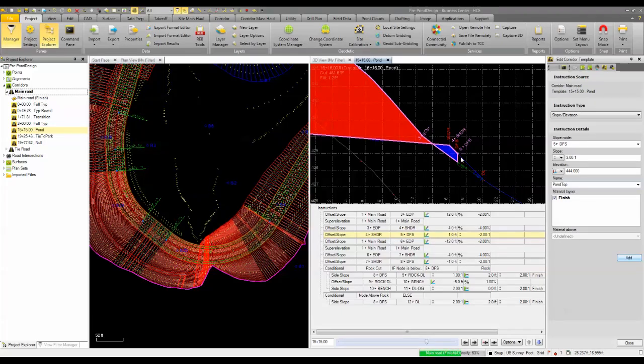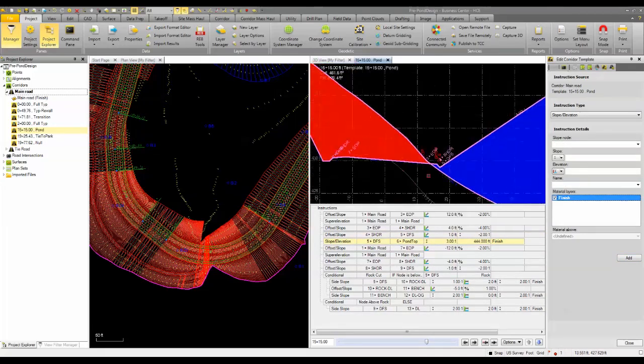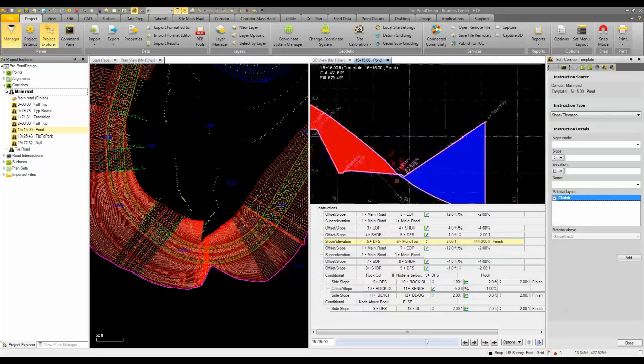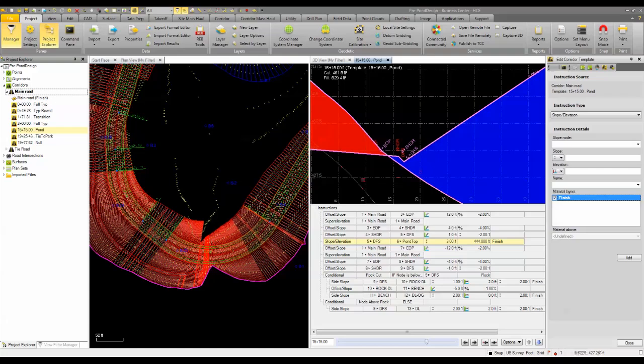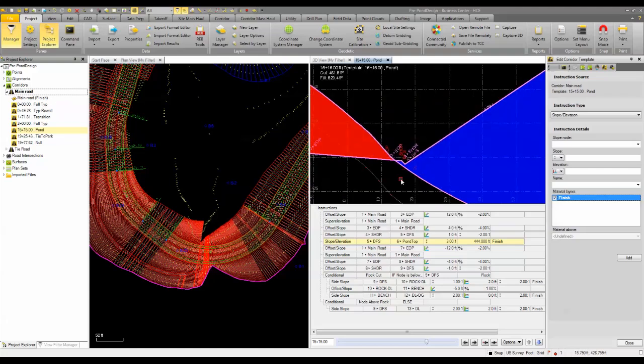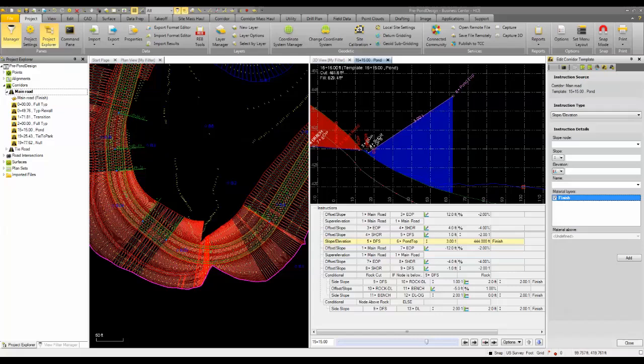So basically what it's tying in is our current design is above our original ground. Okay, so our rock is here, and our original ground is, you can see it, floating down through here. Okay, so that's where we're tying in. So our 0.6 is above the original ground here, so we're going to have to create a berm here and then tie it back into original ground.